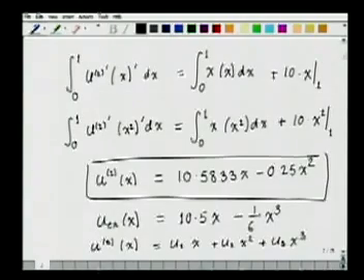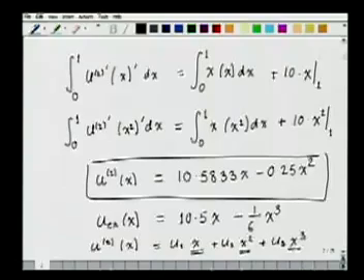So what the Rayleigh-Ritz method has done for us is that by taking these appropriate functions, which we had called our basis functions, which are polynomial functions x, x squared and x cubed, we have been able to recover the exact solution for this particular problem using a 3-term solution.